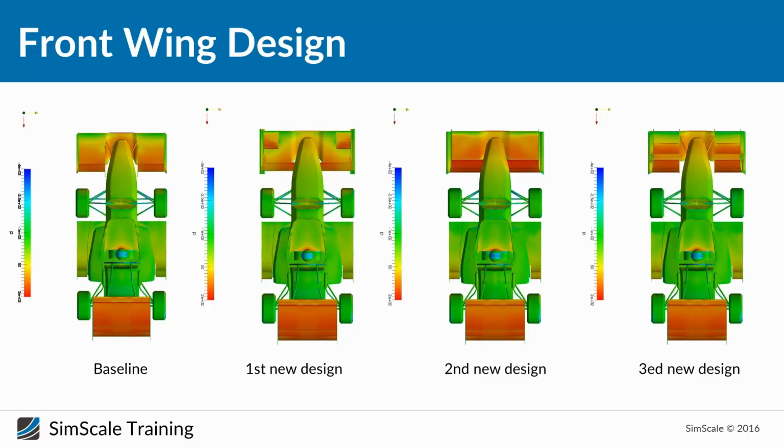with 3 elements. And we can see clearly that this wing generates really high pressure from the top, especially in the second and the third element of the front wing, which are the flaps. And I believe this is because they face the free stream, so that's why we have high pressure over there.